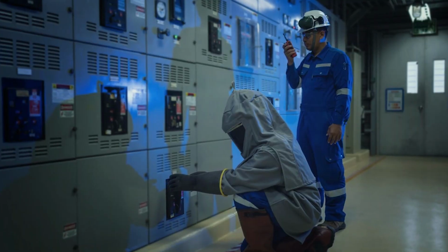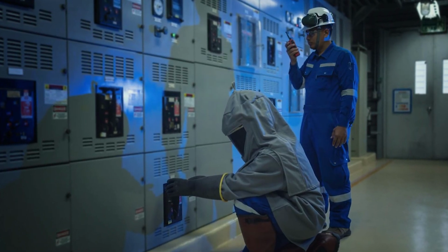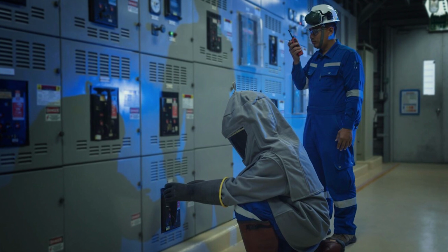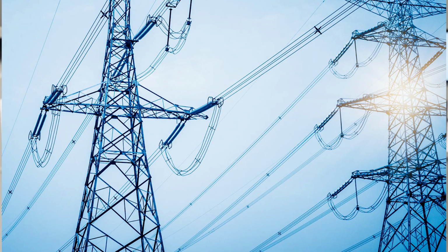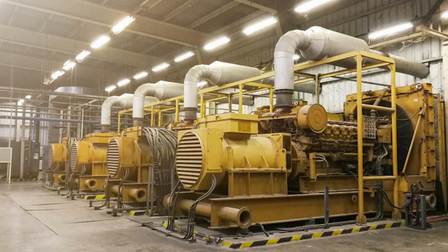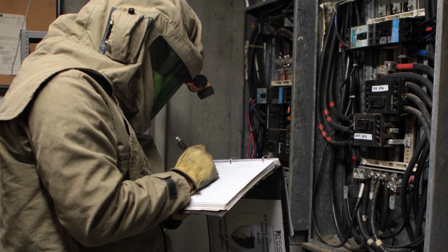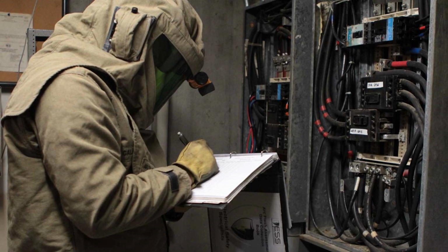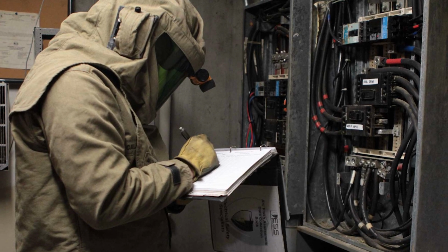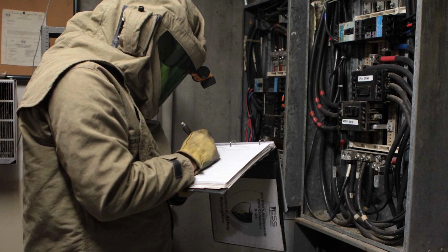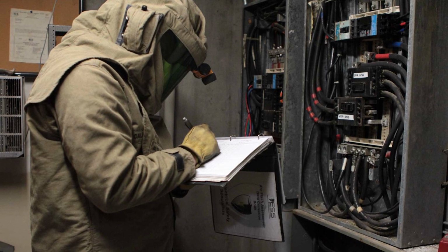It gets very technical in those equations, so I don't recommend diving into them and trying to do them by hand, but also it gets technical from the perspective of what's your system currently running in state-wise? Are you running on utility power? Are you running on generator power? Do you have motors turned on right now that can regenerate current back into the fault, or are they all turned off? Those all will affect that analysis, and ultimately the software and the engineer doing that study in the background takes all that into account to determine what's the worst case energy that could be released.